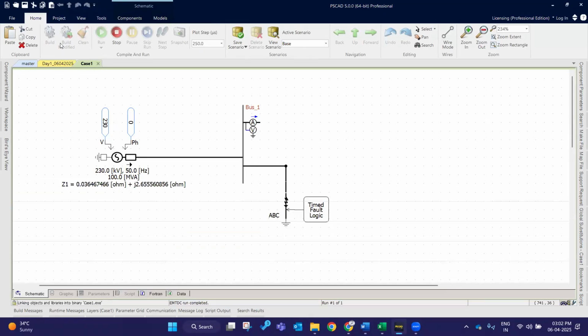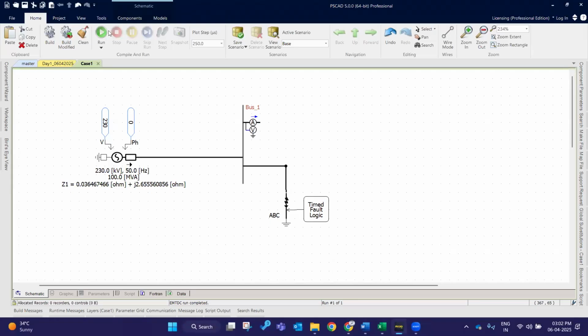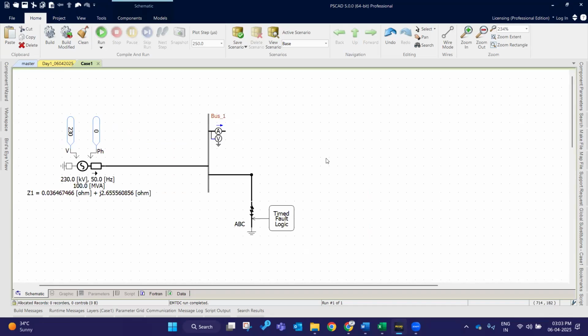Sorry, for this we want to use the build option. I directly performed the run. Yes, it is running. Yes, my simulation completed actually, but we haven't defined the signal, or any channel or plot, anything. We haven't captured anything. So now it is holding the value, but we cannot display it, right? So before running itself, we want to place the corresponding signals, channels, graphs, everything we want to mention.